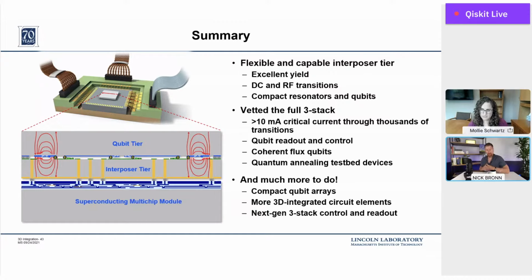So instead of the density and thermal management you care about for classical processors, here you care about having electromagnetically engineered 50 ohm transmission lines so you don't get spurious reflections that can cause crosstalk. You care about everything being superconducting, like you said, you're proximatizing the underbump metallic, for example, which was going to be one of my questions. And you do care about thermal management because you do need to get these cold. So I was wondering if I could get your perspective on the differences, or your take on superconducting qubit integration.